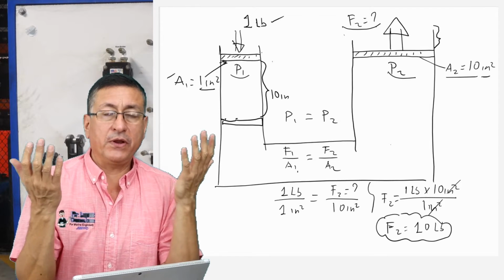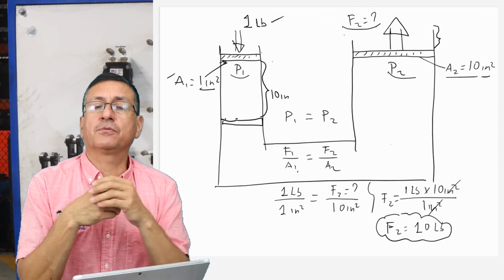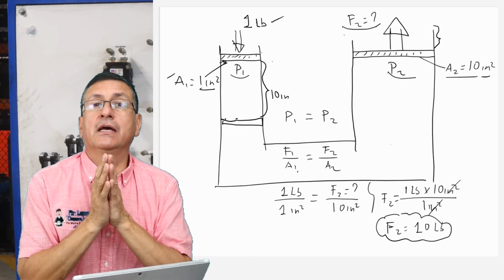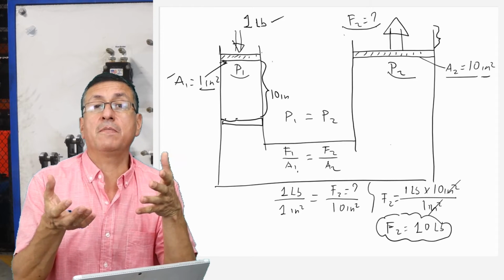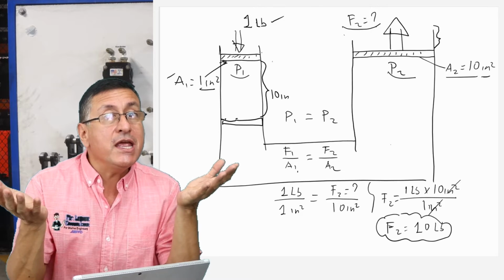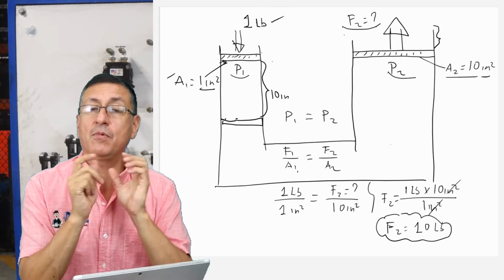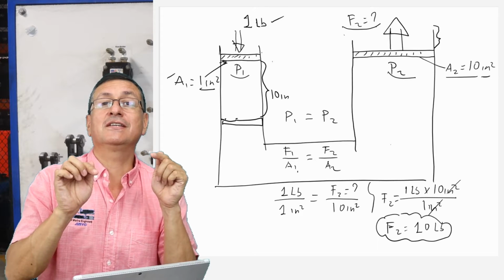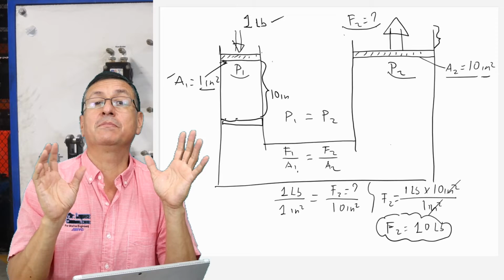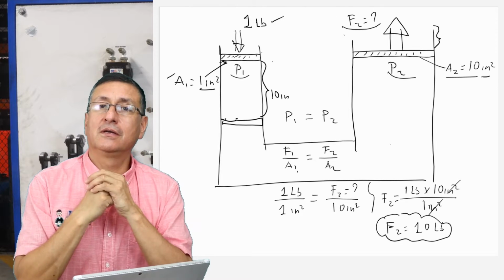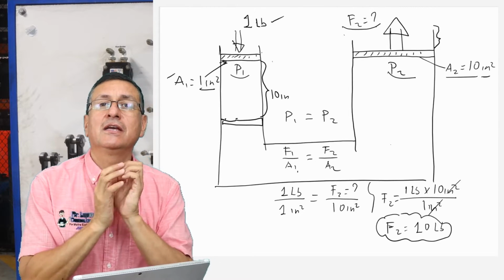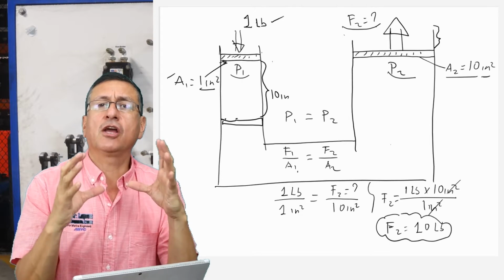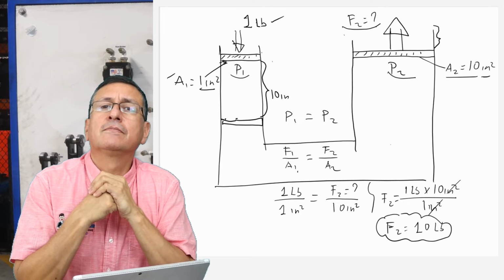Yes, the coolant system. The coolant system is supposed to be hermetic, closed. You remember in our previous courses of gasoline and diesel, I explained the coolant system in detail. And I mentioned several times that you never need to replace the amount of coolant in your car, only if you have a leak. At the moment that you have a leak, the internal pressure of the system is not the same, it's not constant, because you have a small hole. In that moment the system is not hermetic, it's not closed. Another perfect example of a completely hermetic, completely closed hydraulic system.